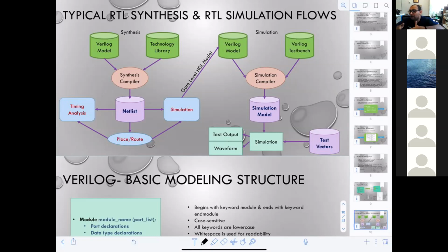If we go more into verification, we can do something called assertion. This assertion means that instead of looking at the waveform with your eyes, you will make rules. If the design, while running the test bench, fails one of them, the whole thing will stop and say, I stopped at this point because something wrong happened. That's called formal verification. Since we just have 15 weeks, I'm going to do my best to cover everything, but as I told you, there is still a part you need to learn from outside resources as well.